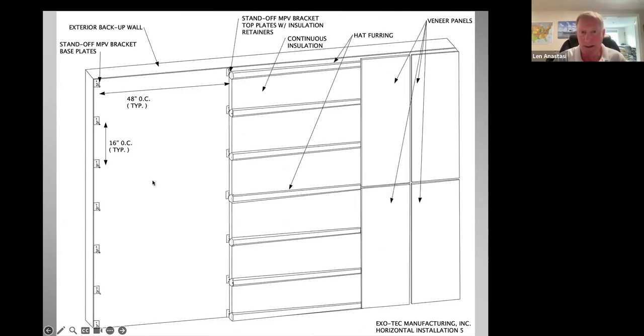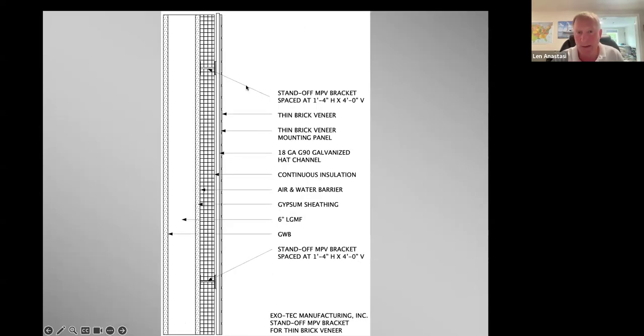For the thin, what they call single ply metal siding, the kind of siding you can hold in your hand and flip your hand back and forth and it'll flop, you can't go more than 16 inches on center for the attachment spacing. So you can go 4 foot on center. And then my rep out in the Denver area said, hey, what about thin brick? Can we do thin brick? I'm like, sure, why not?